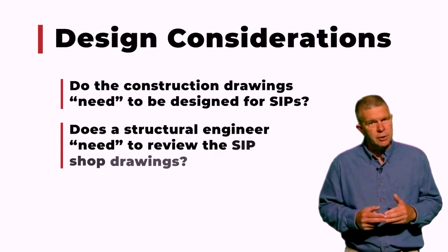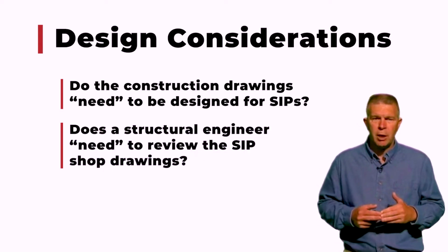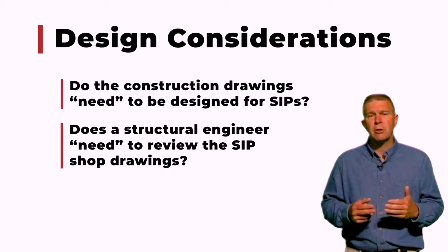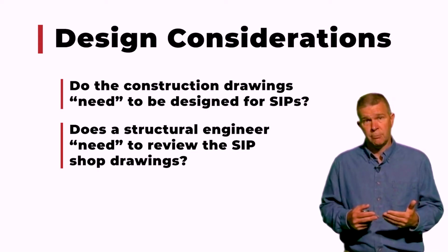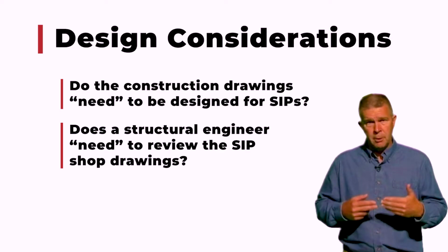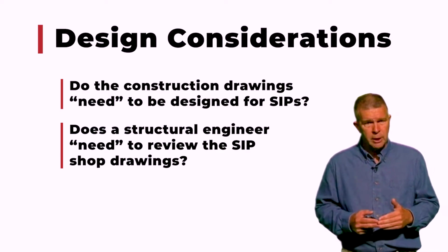You also need to ask yourself right off the bat, when you look at a set of drawings, does the structural engineer need to review these SIP shop drawings? And that's something that has to do with the municipality and the code officials that you're working with.